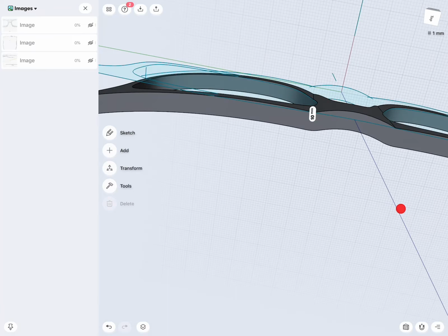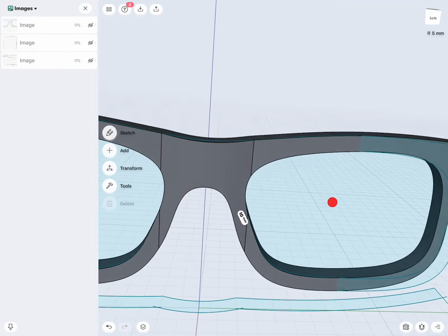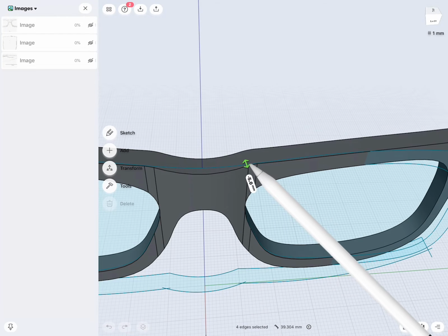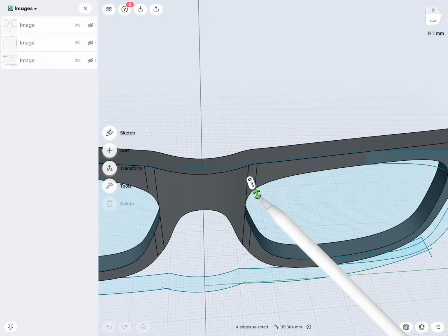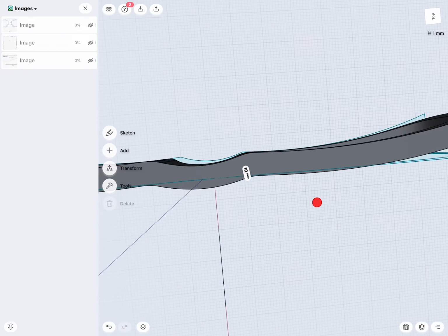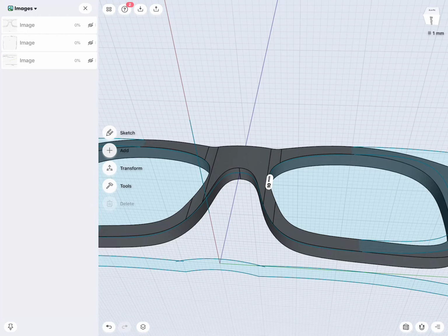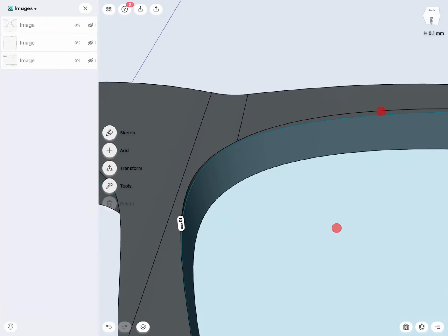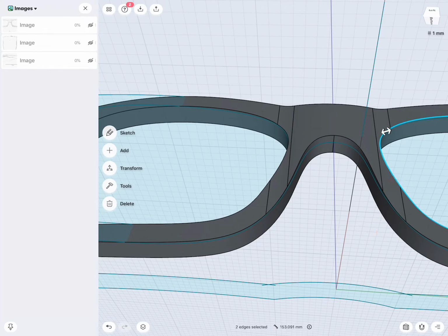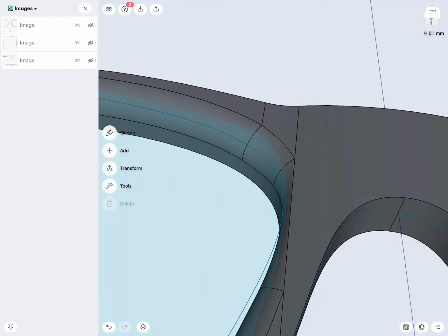Nice. So that looks actually a lot more comfortable, and we will do the same here. So the correct movement, let's do a 10 too. So it's a little bit bigger and a little bit tighter. So why did I fillet these edges? Well, first for comfort, but also this edge is now tangent better to this edge, and I can select these edges and fillet those two later.